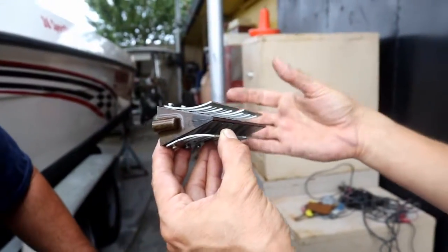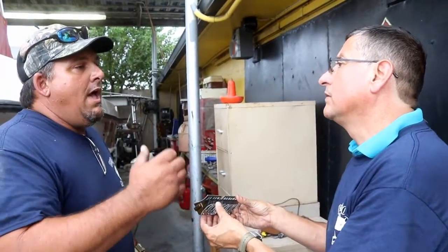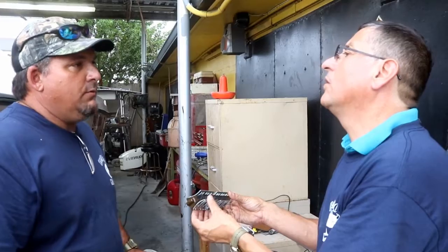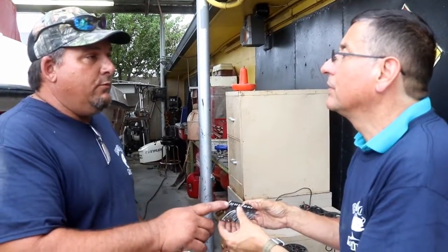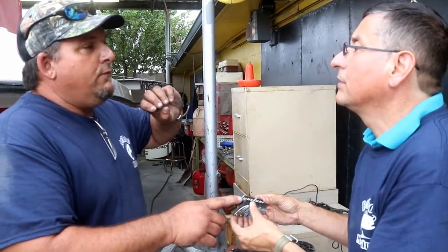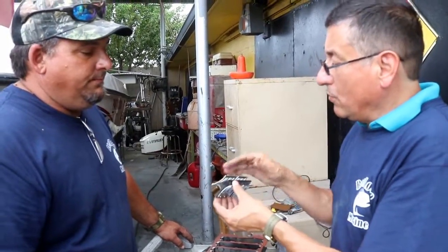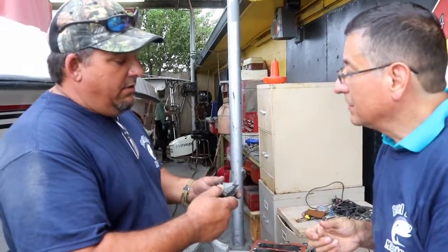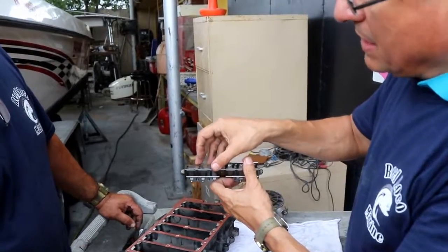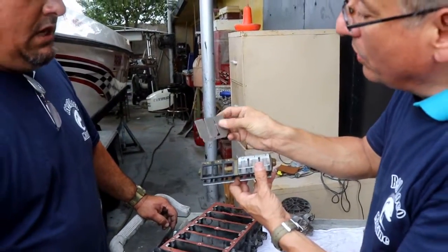It closes. So only that way. If you didn't have that closed, what happens is you'll have low compression. A symptom of a bad reed valve would be that you would see air and fuel spitting out of the intake. That's the symptom, and you have low compression. And what is the enemy of those elements? The enemy is any debris coming in here, and water. They start corroding, and corroded, it won't seal properly.